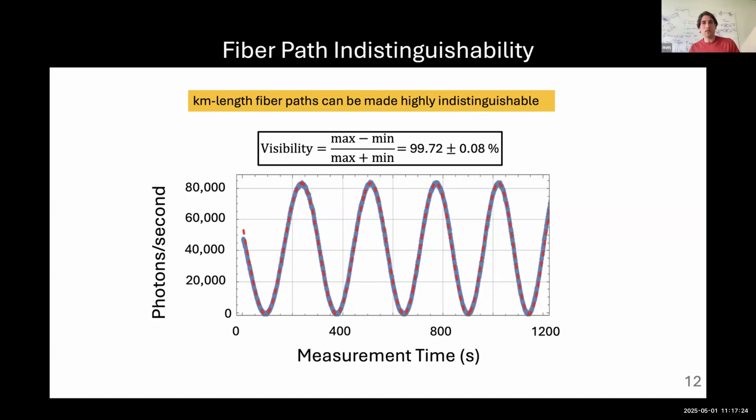So we are using, I mean, it depends on the system, the fiber you're sending through. The fiber we use is this nice armored fiber. It's actually meant for snaking through conduits outside. It's rat proof. It has a nice big metal jacket, and that holds the polarization pretty constant.